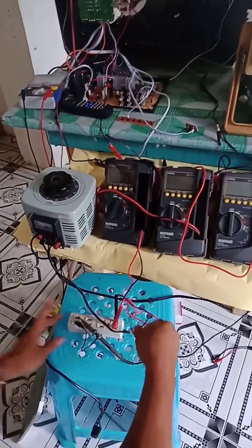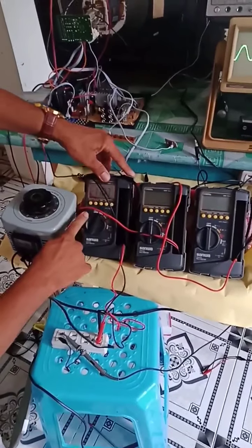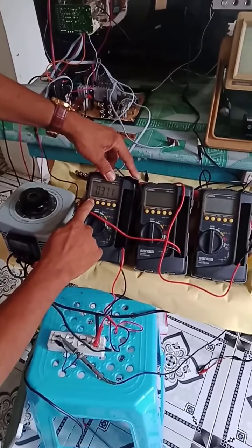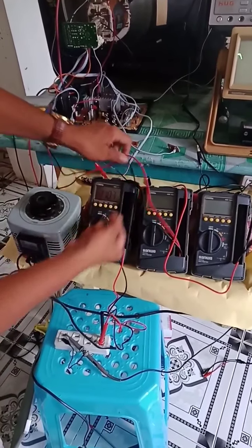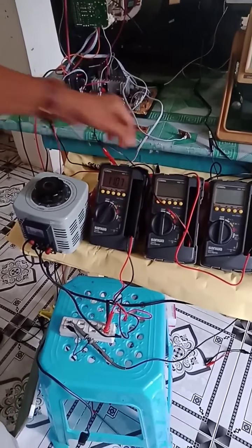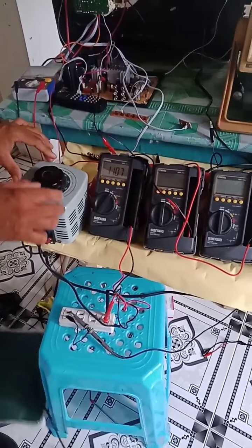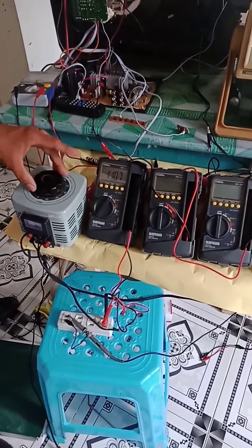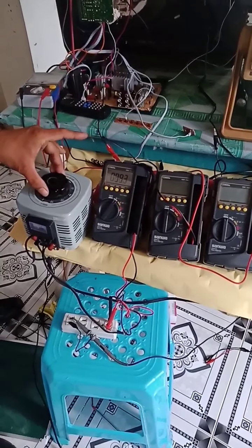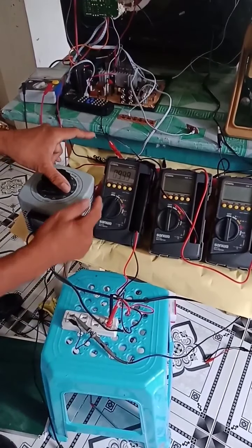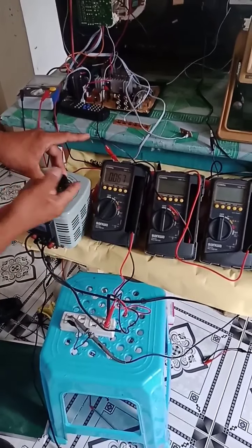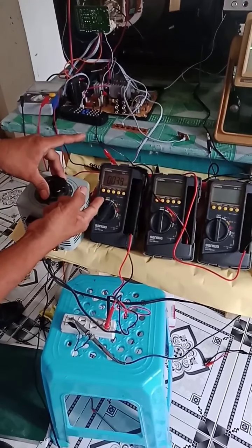Okay, we will set this to AC volts. Okay, the AC voltmeter now is at AC setting. Now, rotating this rotor shaft of a variac transformer will also vary the voltage at the output. Okay? The minimum level actually is almost 0 volt.